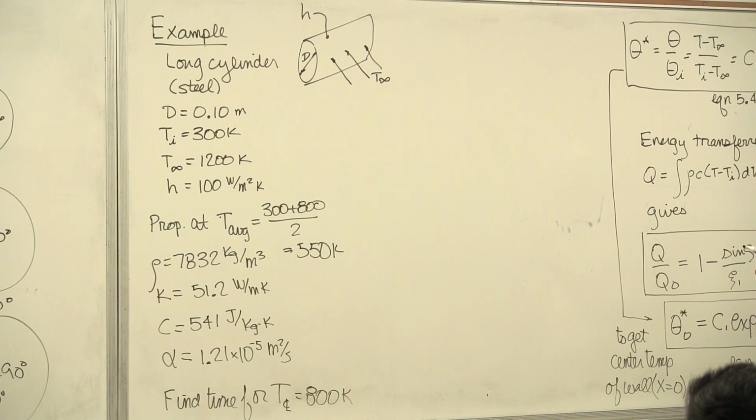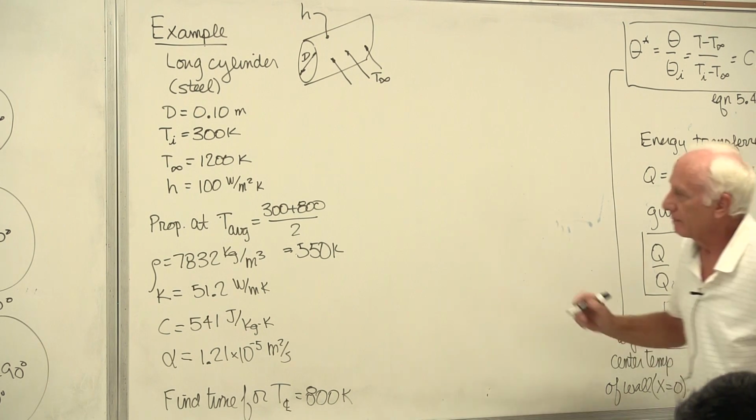That's always the next step. Fluid mechanics, you've got flow in a pipeline. First step, always calculate Reynolds number. Is it turbulent? Is it laminar? This is heat transfer. Always first step in transient: check the Biot number. Can I use lump heat capacity or no? Okay, so Biot number.